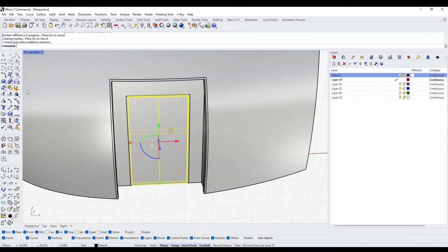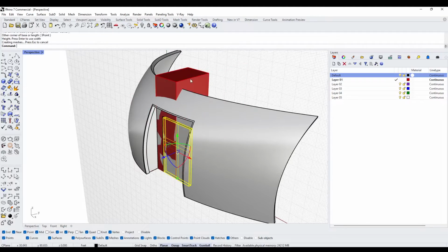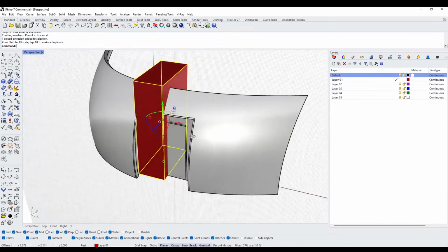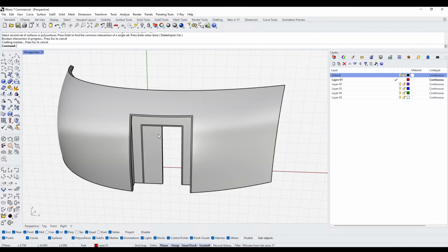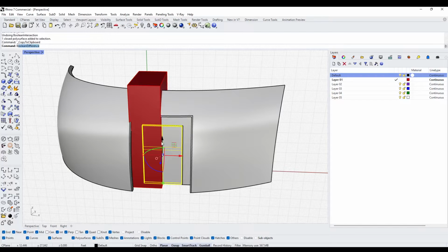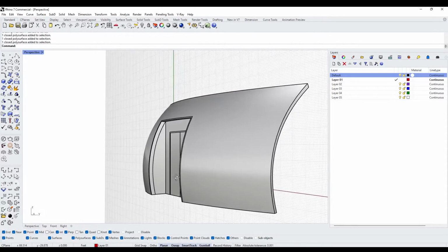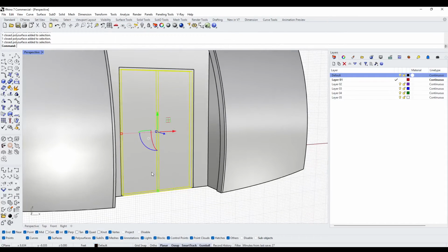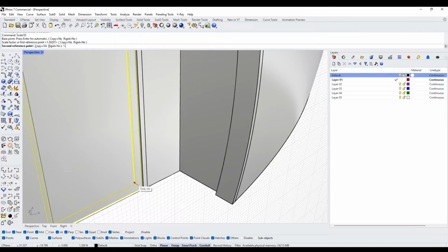And lastly, if it's going to be a pair of doors, I'll create a box that intersects halfway, then do Boolean intersection. Then we have to copy the door, then Boolean intersection with this one, then paste and Boolean difference the one before. So a pair of doors that are here, and we can scale in one dimension between the center and the outside, and we'll do 1.5. We'll do 0.75.